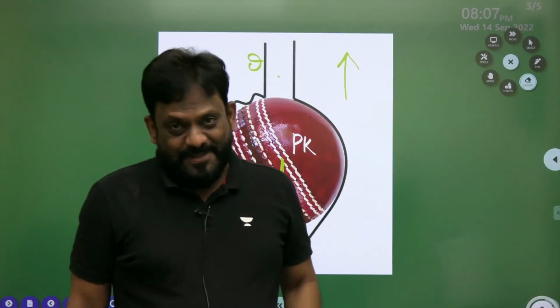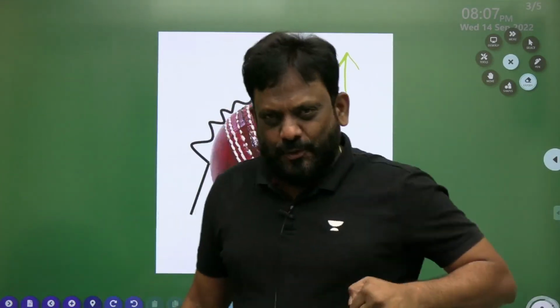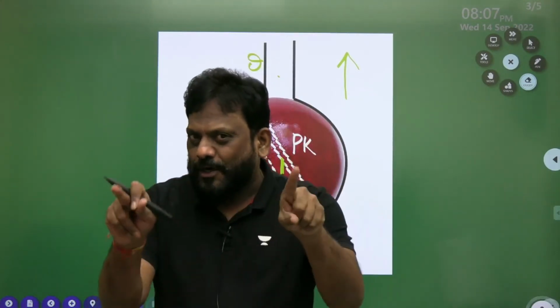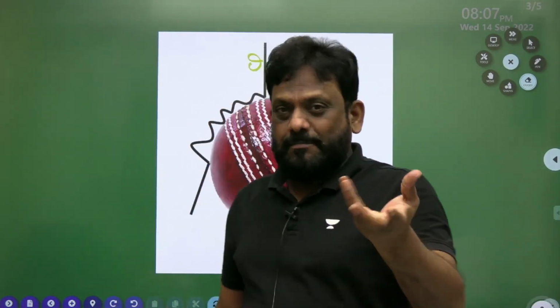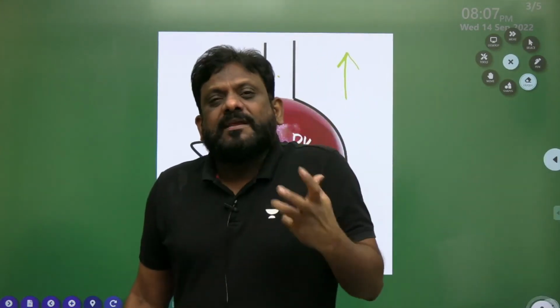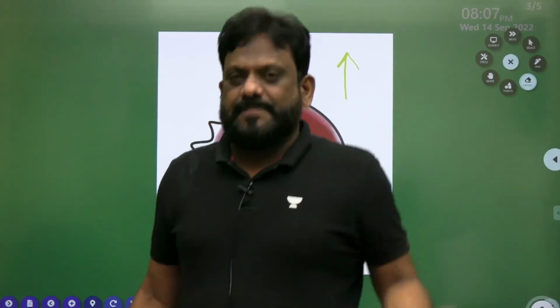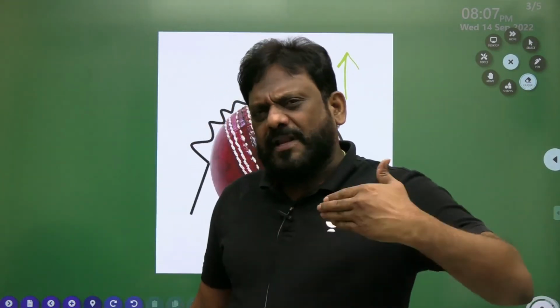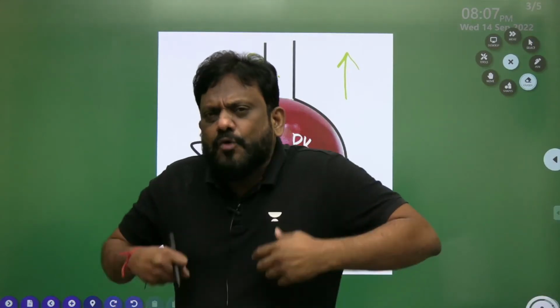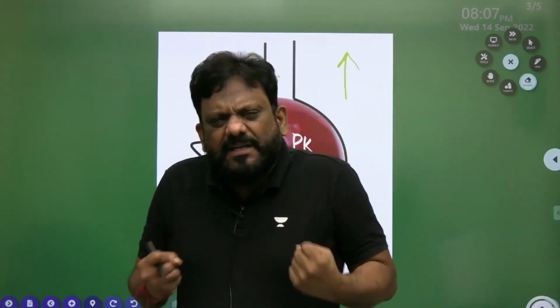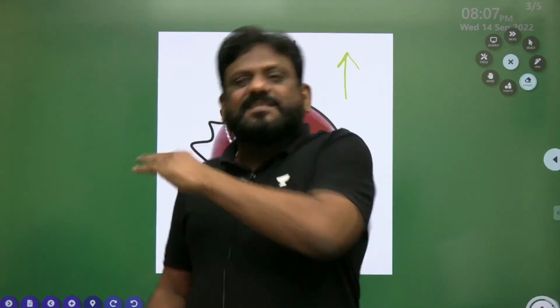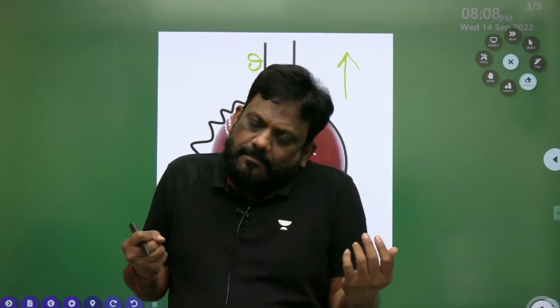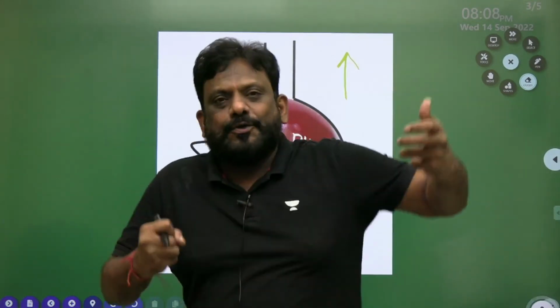Because the ball is new. Look carefully. Your teacher has told you, I taught you very clearly when I was teaching boundary layer theory. One question I solved. Do you remember? I don't remember the question number, but I taught you which boundary layer is least susceptible to separation. Which boundary layer can be separated in a tough manner? Turbulent boundary layer. Laminar boundary layer, because of less energy, because of no mixing of fluid particles, the momentum is not supporting, thereby it separates rather easily. Due to mixing in turbulent flow, see, for example, you are dull, and your friend is supporting you, re-energizing.